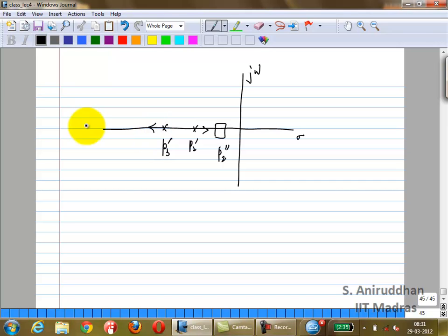Okay? But now you have one more thing thrown into the mix. You have P1. What happens to P1? P1 is going to move in. That is your Miller. Okay? Is that right? So what happens? So let's say you add the Miller capacitance C and you keep increasing the value. So the poles move. What happens? So P3 prime moves left, P1 moves right.